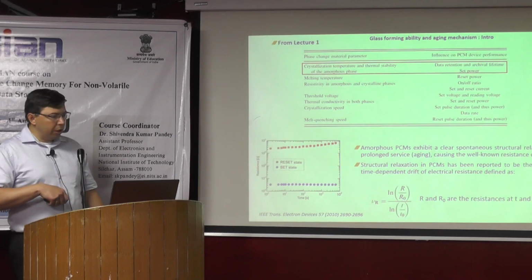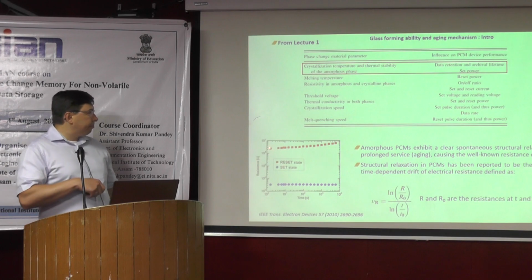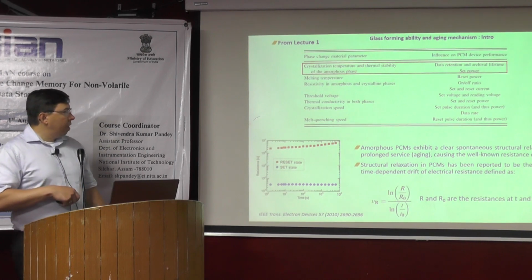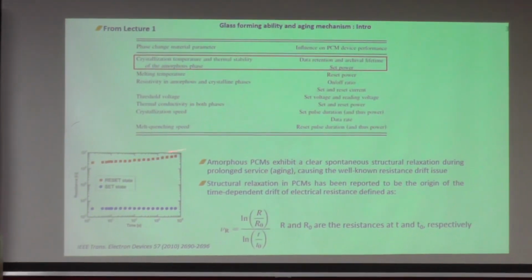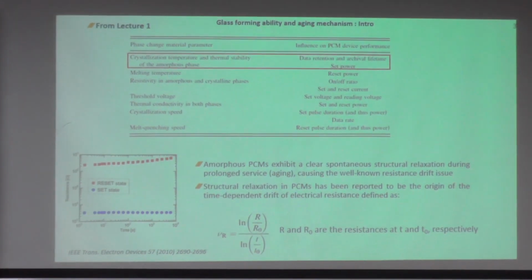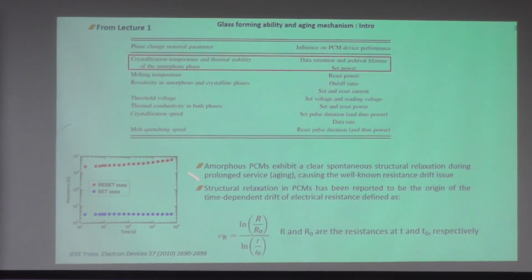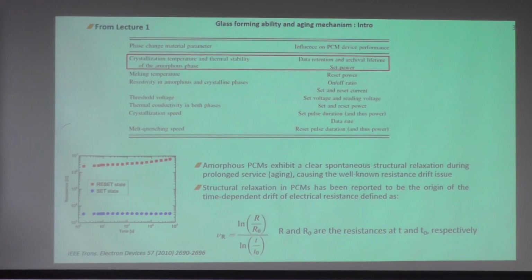Here this shows you the graph from the first lecture, and this is the low resistance state. The resistance does not change over time, and here the resistance drift is changing, and we can see it's going up. So here you see the resistance increases, and if we make a conductivity measurement, the conductivity decreases. And we see here the relaxation of the amorphous state, but not towards the crystalline state. Otherwise, we would see the change of the resistance in this direction.